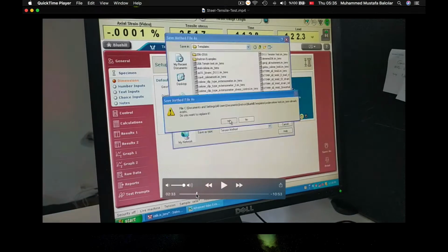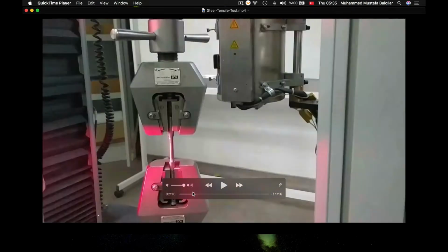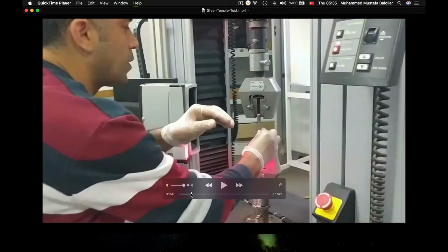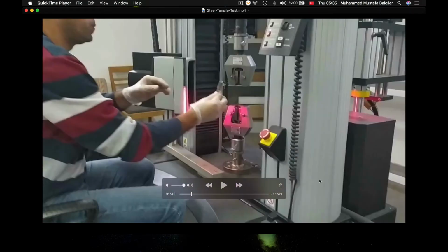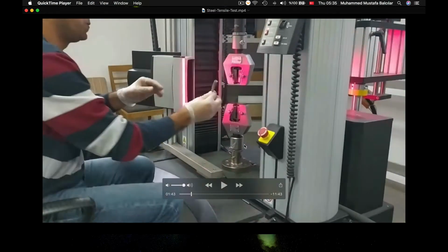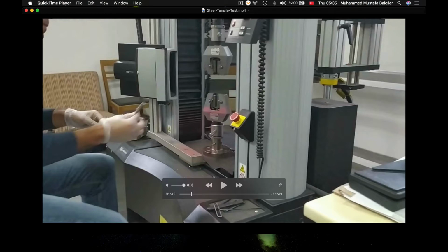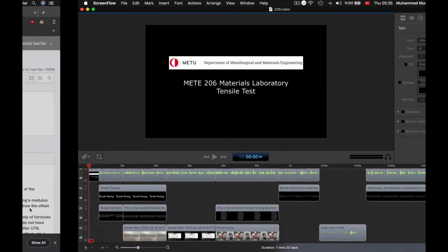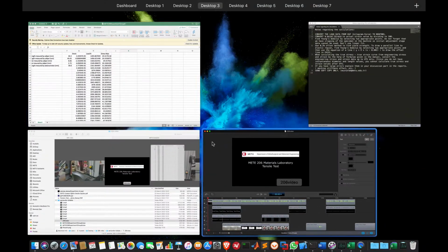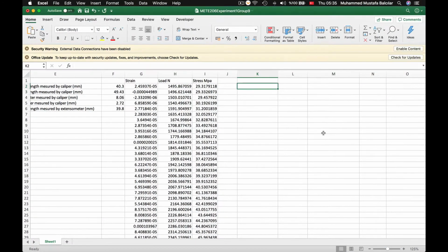Besides that, if you look at the whole machine itself, okay, this machine is also constructed from different materials, right? So we will have the elongation of the machine itself as well. So that also influences the elastic range, elongation and stress values, load values, and we call that effect machine stiffness.